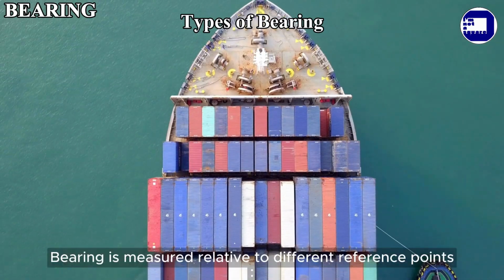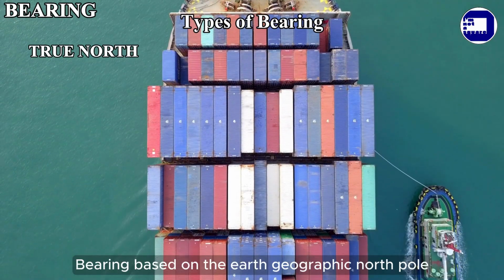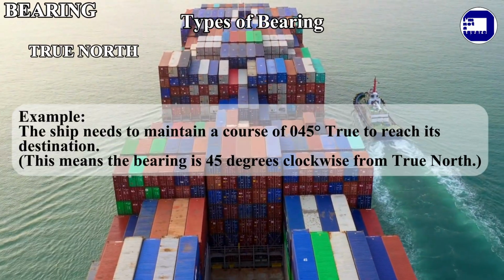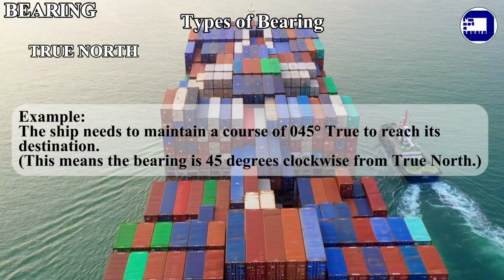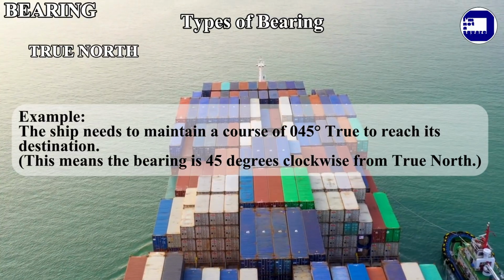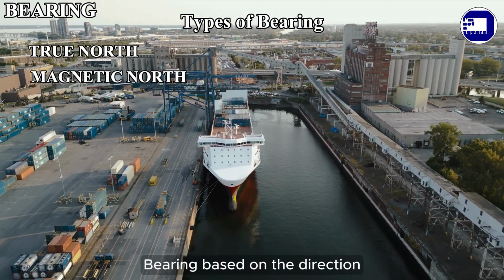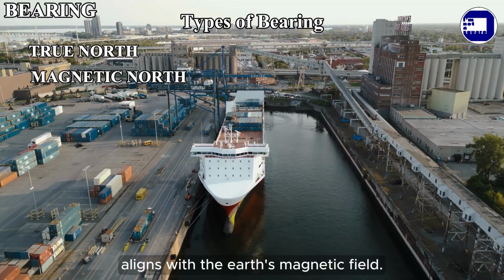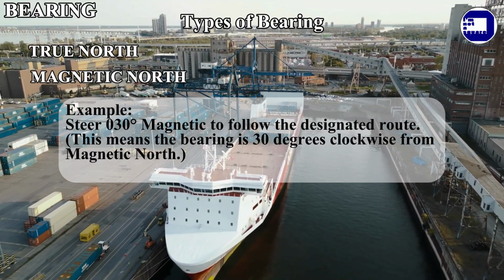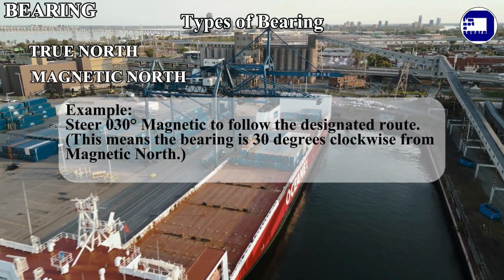Types of bearing. Bearing is measured relative to different reference points. True north. Bearing based on the Earth's geographic North Pole measured clockwise from 000 degrees. Example, the ship needs to maintain a course of 045 degrees true to reach its destination. This means the bearing is 45 degrees clockwise from true north. Magnetic north. Bearing based on the direction a magnetic compass aligns with the Earth's magnetic field. Example, steer 030 degrees magnetic to follow the designated route. This means the bearing is 30 degrees clockwise from magnetic north.